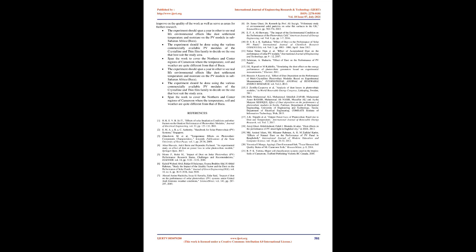It is recommended that, for proper sizing of solar PV systems, consideration of the influence of dust on the output should be taken into account in the given locality, given the fact backed up by our literature review that different dust types, hence profiles, affect panels differently. By so doing, it is advised to add a factor to cater for this at the design stage, program preventive maintenance to ensure continuous optimum output, or both of them.